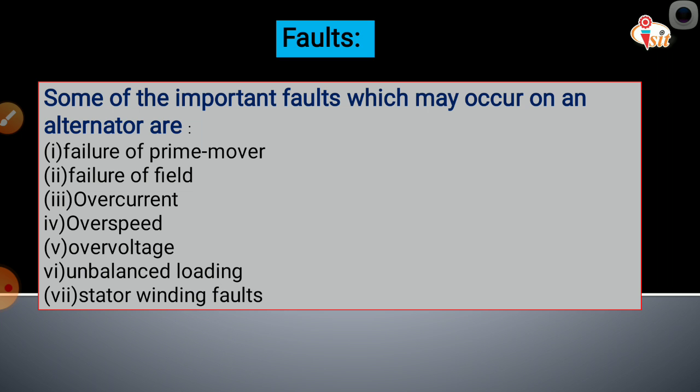It is mainly used for the protection of small generators. In balanced earth fault protection, the same set of CTs is used, but here the relay coil is connected in the secondary windings of the CTs, and when the fault occurs within the restricted portion, it gives a signal to the circuit breaker for its operation. So this is the third type of protection, balanced earth fault protection, also called restricted earth fault protection, since it provides protection only in the restricted region.